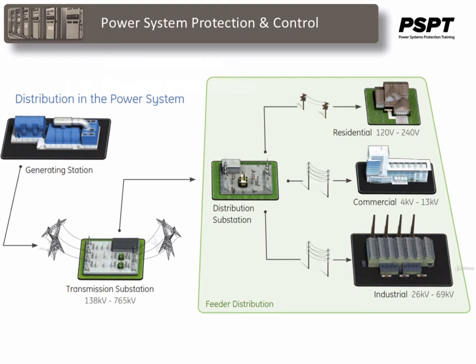Since the transmission system is typically rated from about 130 kV up to, could be as high as 700 kV, substation step-down transformers are used to bring the voltage levels down to under 50 kV levels for distribution to the customers. As the distribution system is rated up to 50 kV, many large industrial end users will be fed at these voltage levels and will supply their own on-site substations that will step down the voltage to more useful voltage levels for the facility.